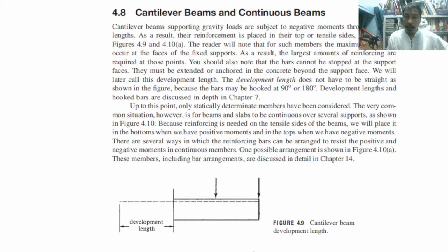So next, very important for our discussion of slab. Notice that we were designing simply supported slabs. Now we are dealing with cantilever and continuous. So continuous on one end, continuous on both ends, and cantilever, right? So obviously, the estimated value of h is equal to 1 over 10 and 1 over 8, right?